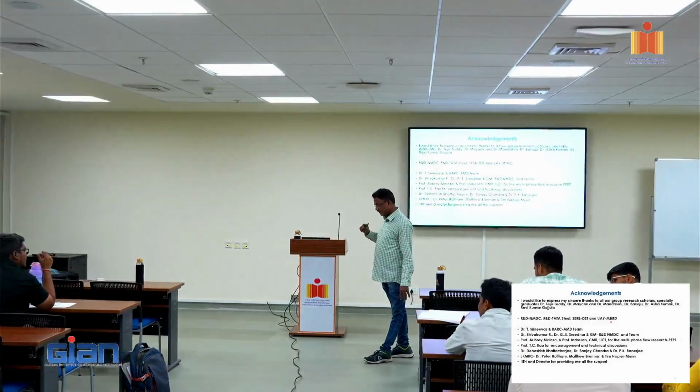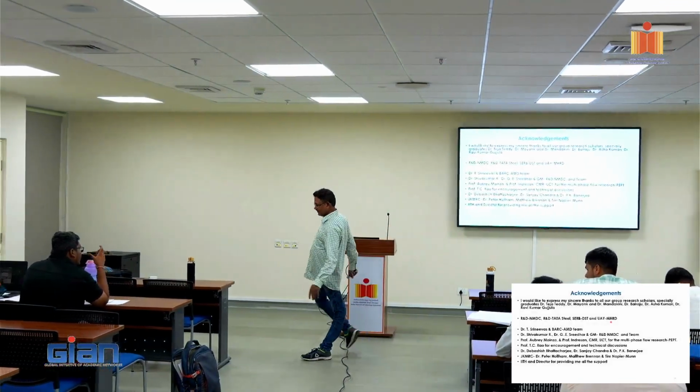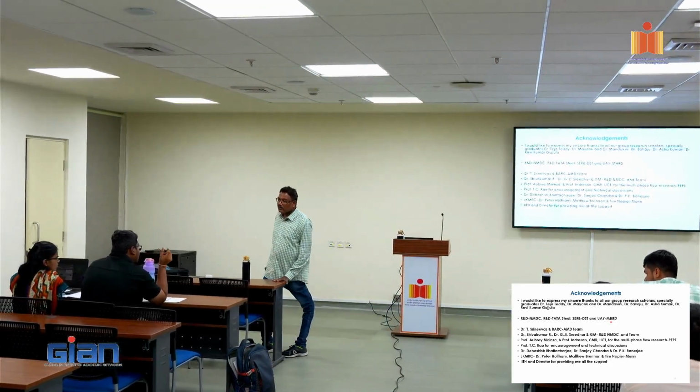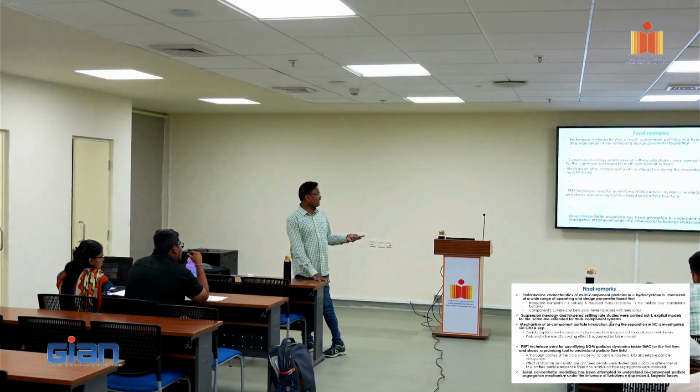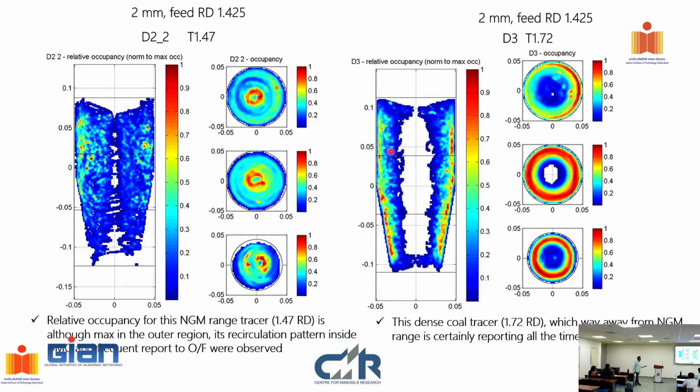So, dense media cyclone. Yes, then we'll be using different material of different size. So the process that we have actually used, I didn't pay much attention to it, but otherwise, you have magnetite, which is the medium. Magnetite fine powder having a specific gravity of 5 is mixed in some proportion with water. Let's say if you want to prepare a 1.5 density medium, volumetrically I can calculate and mix it. That mixture is prepared in a sump and circulated thoroughly to make it homogeneous.